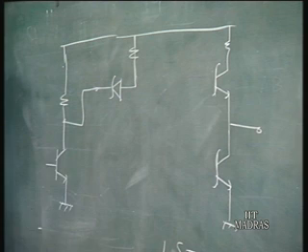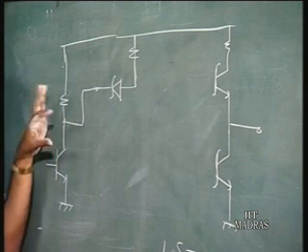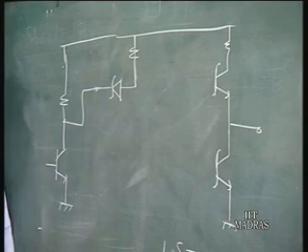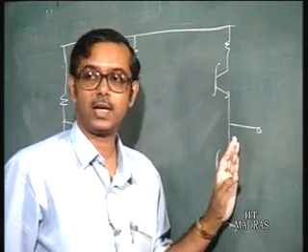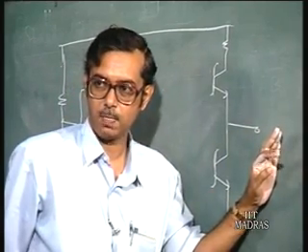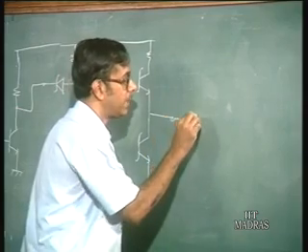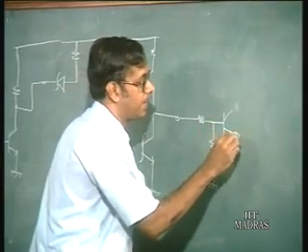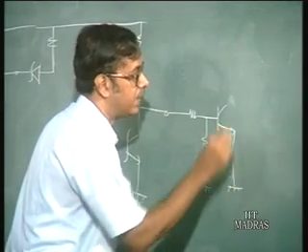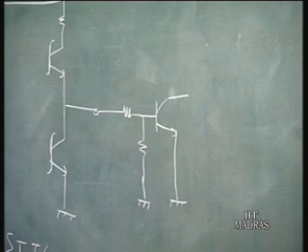So it is very simple, you just connect a resistance here, and you can connect it as input to the TTL. On the other side, if you want to give the LSTTL output as input to I squared L, what do you do? Basically you make a sort of potential divider type of circuit, and this can be fed as input to the I squared L.